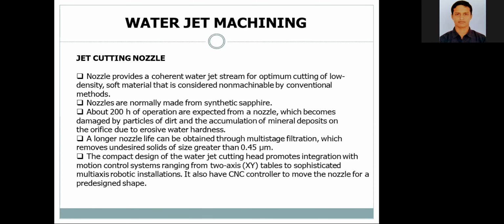The cutting nozzle. The cutting nozzle provides a coherent water jet stream for optimum cutting of low density soft material that is considered non machinable by conventional methods. Nozzles are normally made from synthetic sapphire.